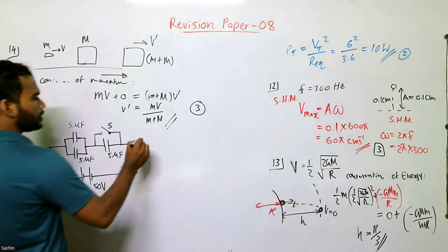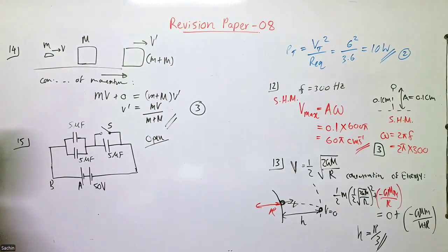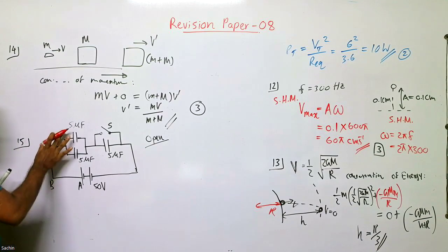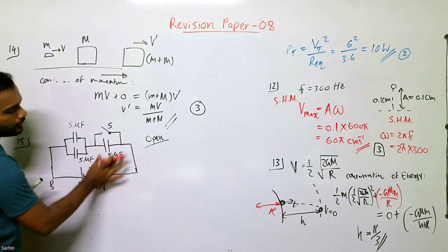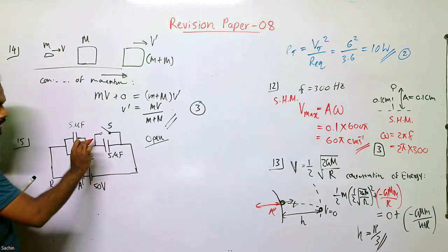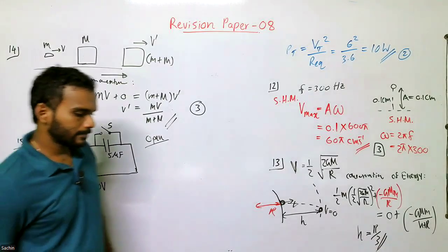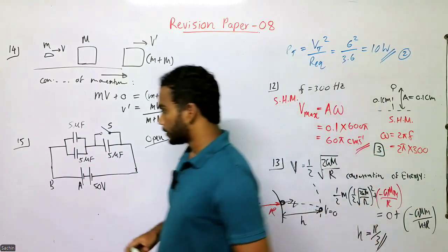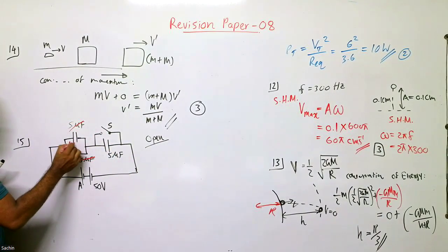Okay. So we will first solve for the open condition. When the switch is open, this system is nothing but two parallel capacitors connected in series with this 5 microfarad. Right? In this part, current does not flow, because this part is open. In capacitors, series and parallel connections work the opposite way to resistors. Right? For parallel connections, we can add. So the equivalent value of these two will be 10.